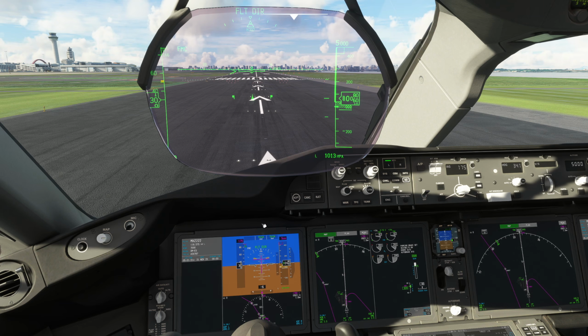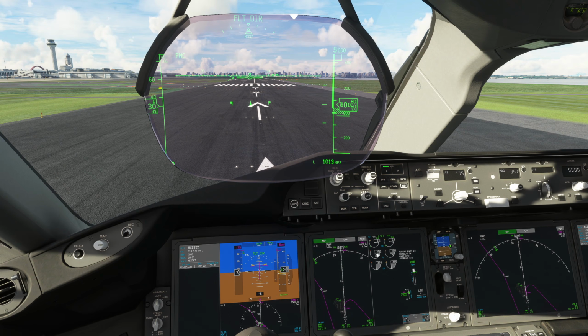After 200 feet above the ground, we can engage the autopilot with the AP button over here. And after 400 feet, the FMAs will all change, and it should engage into its LNAV mode. So we should then see autopilot available if you want it, and you can also see LNAV and VNAV engage as the vertical modes instead of TOGA, so it will swap out of TOGA at that point. As we reach 1500 feet, it will bring the thrust from takeoff thrust back to climb 2 thrust as we have asked for, and of course we'll be following our magenta line, and then it will accelerate and set the new target speed.